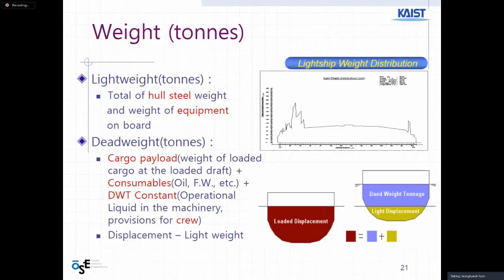And then displacement is coming from buoyancy, and buoyancy is coming from the pressure from the water. Right? That should be balanced together. Right? Weight, including all cargo and others, right? Whole cargo, and so this one can be several different curves: lightweight curve, cargo curve, and altogether curve. And also loading condition.